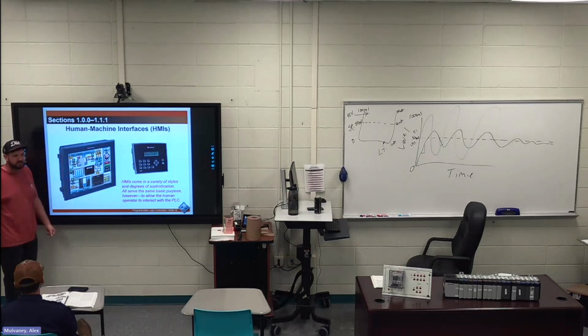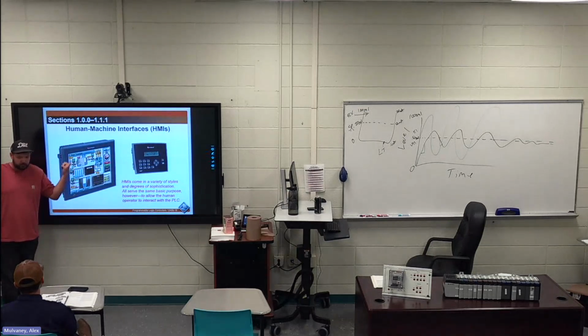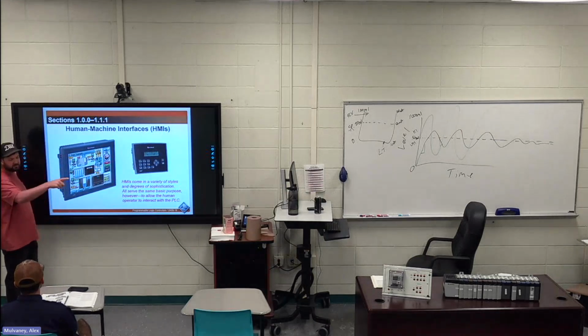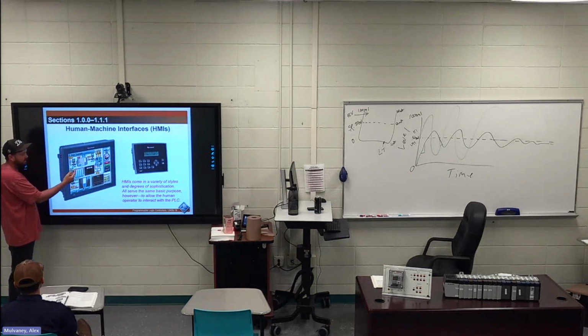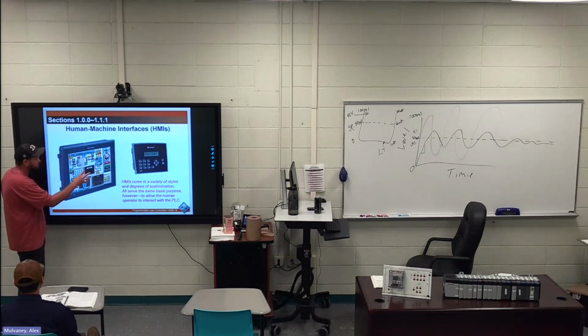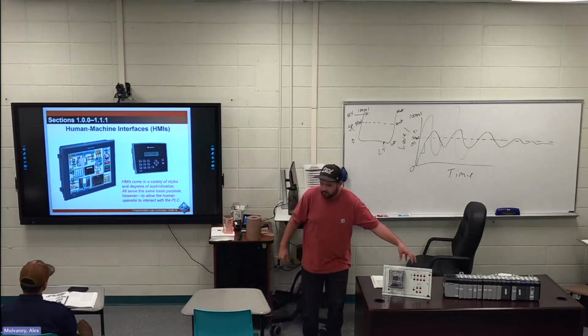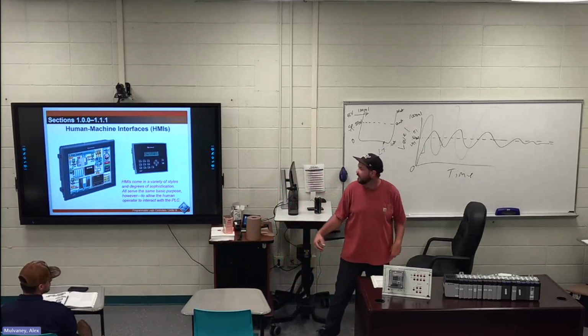All that would normally be a normally open contact on a contactor for a motor. You have an input that says my motor is on going to my PLC, and you tie that address to this, and it turns on an animation, say, and a light or something like that, says it's spinning. And you just have a lot of these stock. I think you can go create your own. I never got to that point where I could create my own, but you just create these screens that make sense for these different plants. Like you have tanks and scales and stuff like that, and you link them all in the programming back to what's going to this. Kind of makes sense.